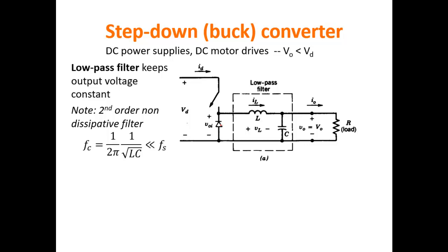Okay? Let us look at the thing in detail. Of course, this is a low-pass filter, a second order low-pass filter. It's relatively easy to compute, because what you need to do in order to compute the transfer function of this low-pass filter is just to compute a voltage partition due to the presence of the capacitor and of the inductor.